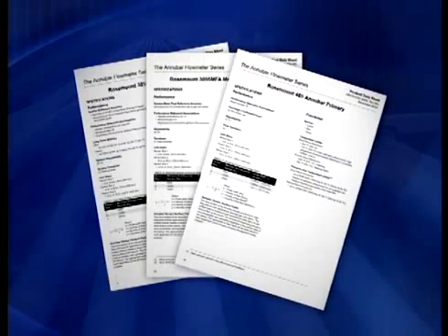If your installation does not have the required straight run, then your Annubar accuracy will vary from published numbers. You should contact a flow specialist for details.